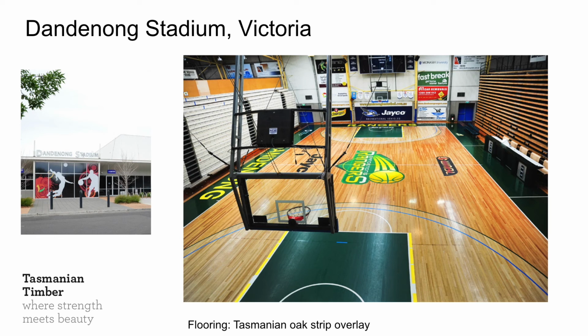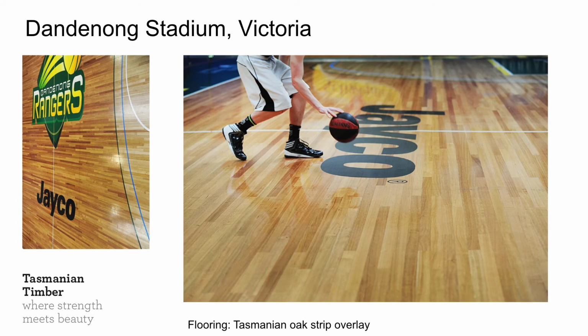We did a job, well, actually the university replaced the floor at a stadium at Newnham, and didn't ask us, they just did it. And they did come and ask us when the whole floor started to rise up in the middle of the gym, and we had them go in on three different occasions and put saw cuts through the whole floor system to give it expansion and to get them to re-ventilate underneath the floor before it settled down. So if you don't do it, you will know about it at some stage. So there's particular details of it. I won't go into any more detail today, but there is solid information on the website about floors.